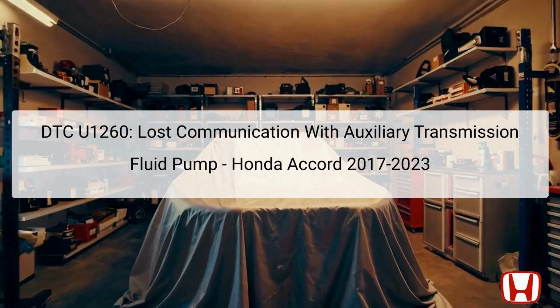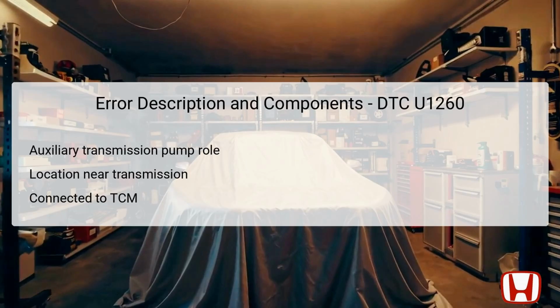The purpose of this presentation is to explore the components affected and the systematic troubleshooting process to resolve the U1260 error code effectively. The U1260 DTC specifically points to lost communication with the auxiliary transmission fluid pump. The auxiliary transmission fluid pump has a critical role in providing the necessary hydraulic force for gear shifting within the continuously variable transmission (CVT) system.